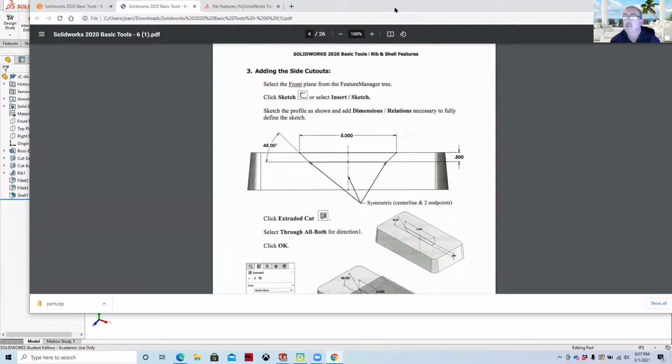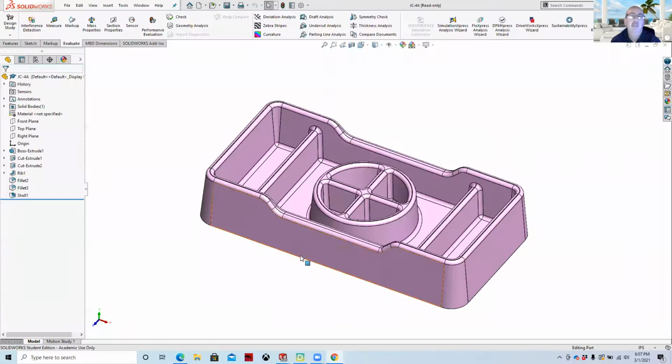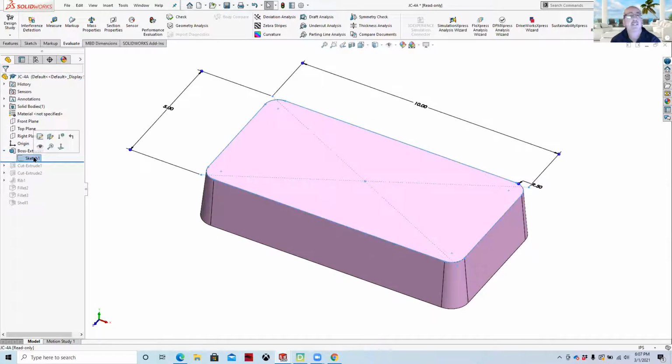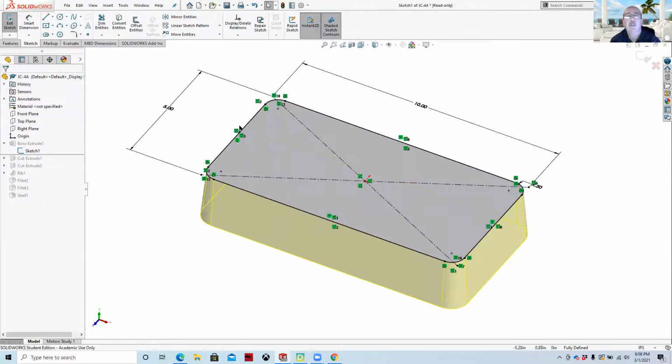And we can take a look at our existing drawing. If you're new to SolidWorks, what you'll find is it's got this bar right here, and you can dial things back. And so we can show how this part was constructed, and you can do this to any file actually, with the boss extrude command. And so here's our sketch right here. If we need to edit it, I can edit it right there. We want to make sure that our sketches are fully defined, meaning that they're all related to the origin and that the SolidWorks software knows where everything is.